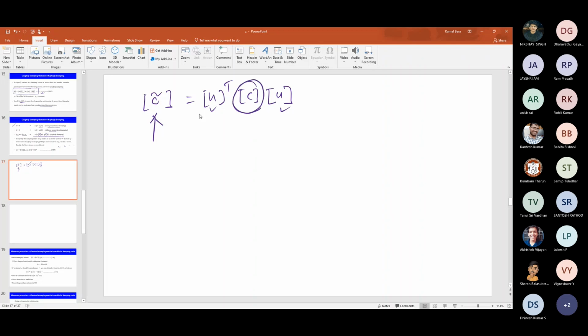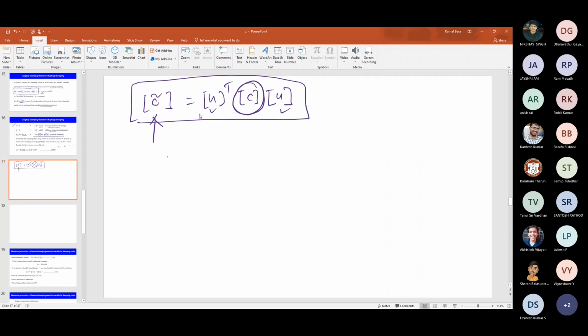Basically, you are trying to construct this matrix, right? So you can actually directly construct the damping matrix from this expression also. How to construct that? Obviously, C will be just taking the pre and post multiplication of the inverse of those matrices, so that is U transpose inverse C tilde U inverse. Am I right or wrong? Correct, right? I want to construct this.